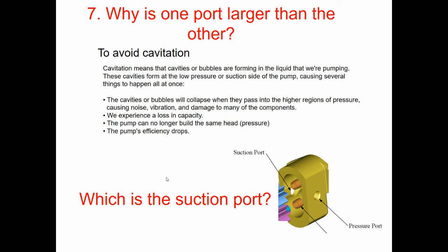And this, of course, is going to cause vibration to happen to the pump itself. This vibration, by the way, is too dangerous. Sometimes it can cause an explosion of the pump if we have the resonance phenomenon. Also, it's going to be pumping bubbles, and this will reduce the efficiency of the pump itself. And also, it can no longer build the same head because it's pushing the air all the time.